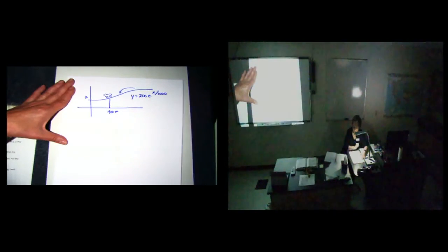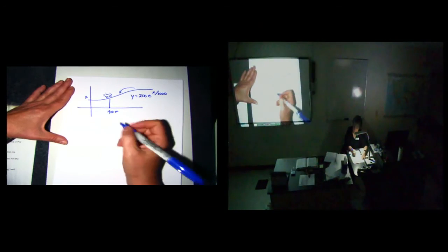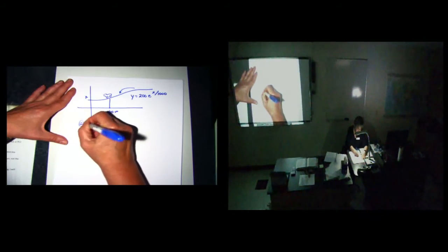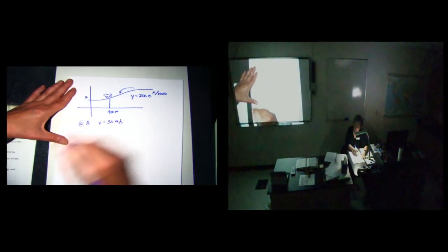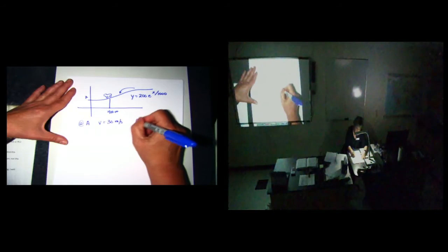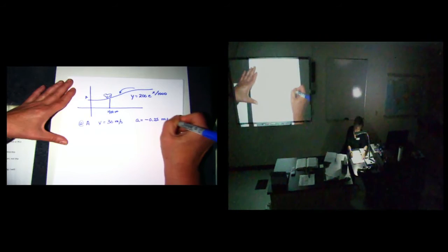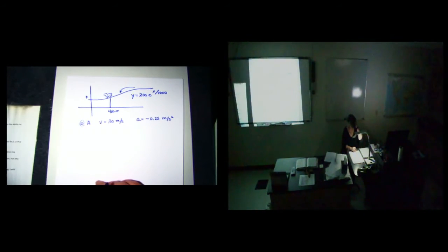That looks like a kinematic equation. It is, it's the same thing. So this is going to be my 30 meters per second squared, plus 2 times my negative 0.25, and my change in position was 412. Is that an a sub t? Yep, it's the tangential acceleration. If I do the arithmetic, I get v_B equal to 26.34.